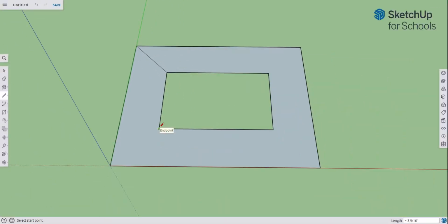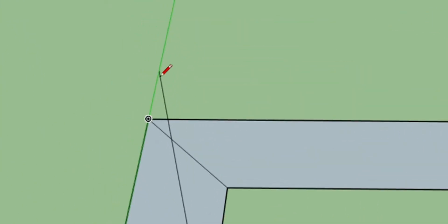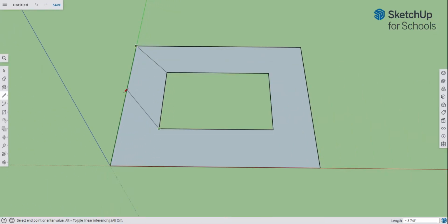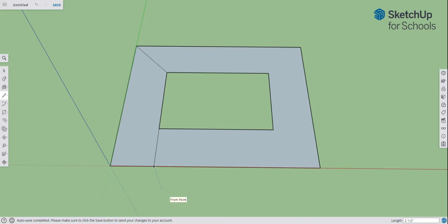All right, here I'm going to do a butt joint. I'm just going to do a straight cut. I'm not going to do the angle. I'm going to do from the end point. I'm going to click on it once, and I'm going to drag it down. Now you'll see the line is green. The reason the line is green is because you see this line up here, this axis that we started along, is parallel. Right here, this green line is parallel. If I get a green line here, I know my line is parallel to that axis too, which is what I want. A nice straight line. I get right to the edge, and I click again, and now that's my first piece of the project there. I'm cutting one miter joint here and one butt joint here for the frame.